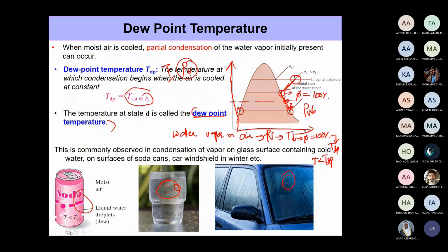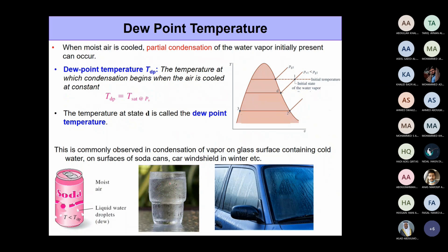So here we said that we notice this water getting condensed on surfaces, right? The water that got condensed here is basically the water vapor from the air that was touching the surface of this glass, or touching the surface of your car windshield and so on. So it is exactly that specific air which is very close to and touching the glass surface that undergoes this process of initially going from its initial temperature to the dew point temperature and then going below the dew point temperature.